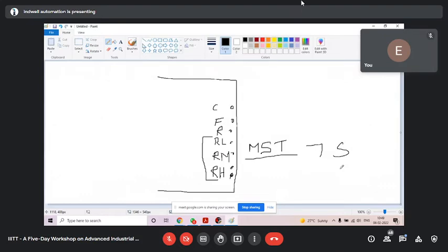Fine. We will have some output, digital output terminals, not analog. Why do we use this? Digital output terminals we use to get feedback from the AC drive. Suppose I want overload feedback: if it is overloaded, a signal should come to the PLC. Or when the motor reaches high speed, we want some signal. Or any condition; some conditions will be given in its user manual.